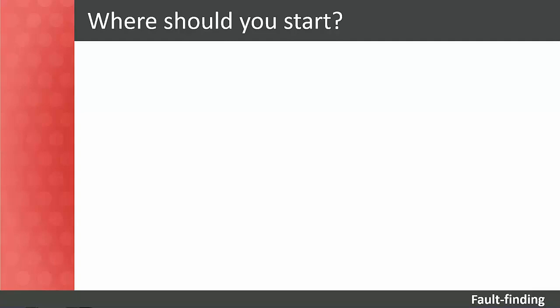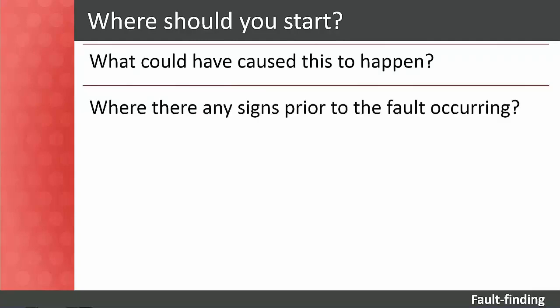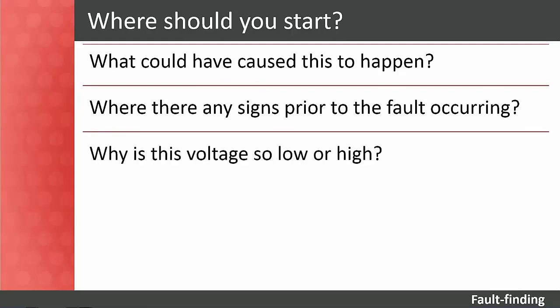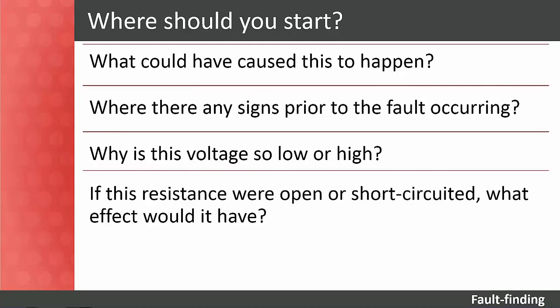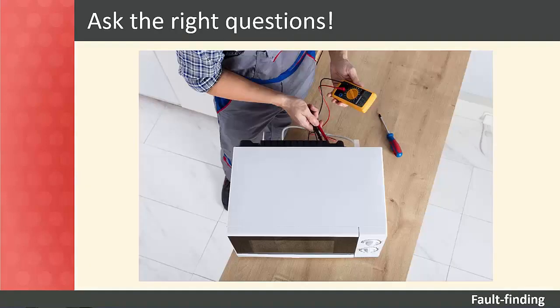Troubleshooting requires the technician to ask questions such as, what could have caused this to happen? Were there any signs prior to the fault occurring? Why is this voltage so low or high? If this resistance were open or short-circuited, what effect would it have on the operation of the circuit that I'm working on? Which area of the equipment could the fault be in? And so on. The ability to ask the right questions is what makes a good repair technician.